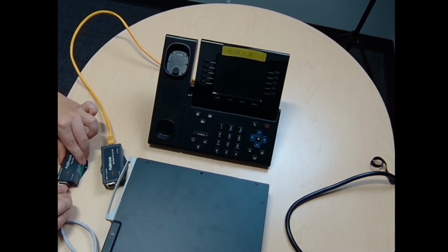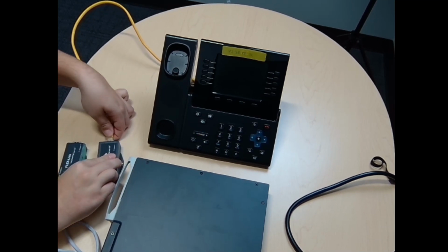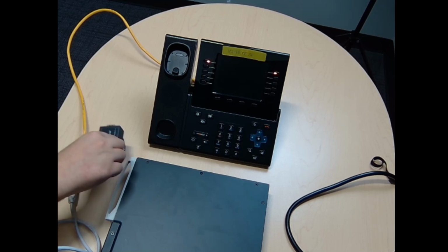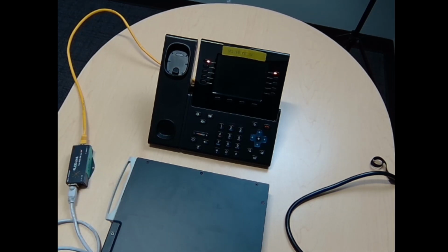We can double check for faulty adapters by replacing each adapter with a known working one and seeing if the device powers up. Replacing an adapter and having the end device power up would indicate that the fault is isolated with the adapter, and if the endpoint does not power up after all of these possibilities are exhausted, then it's likely caused by the endpoint not functioning properly.